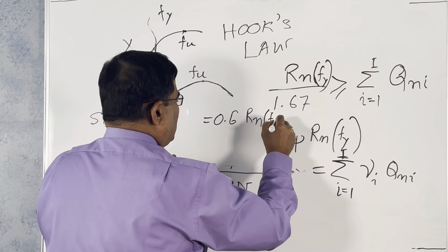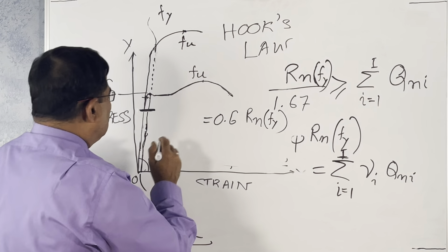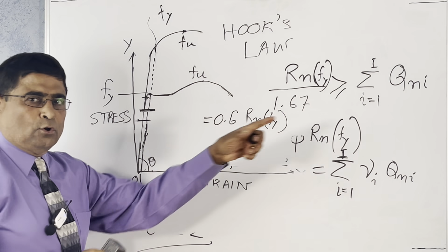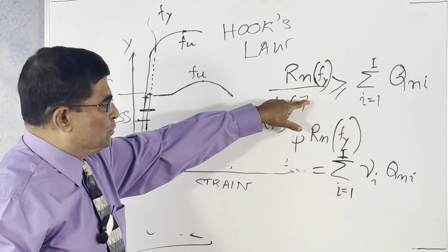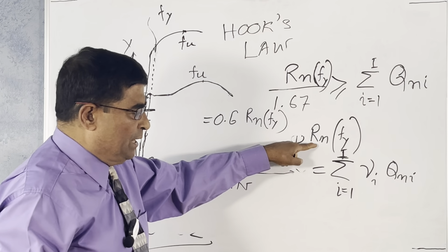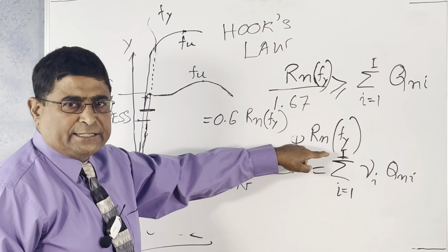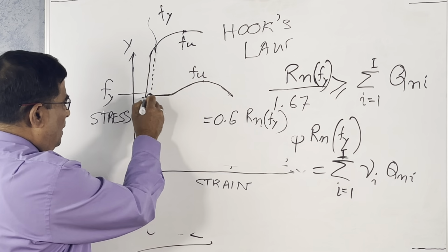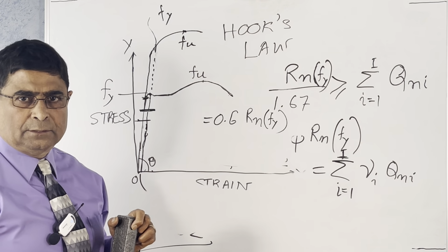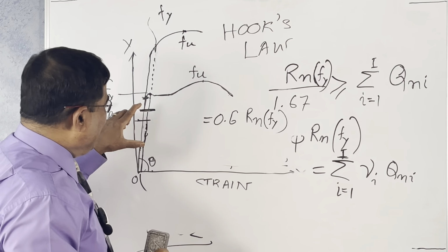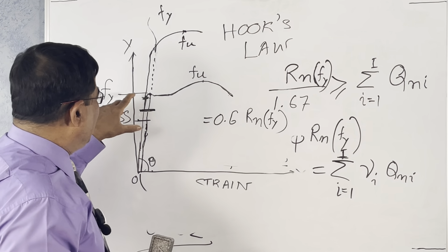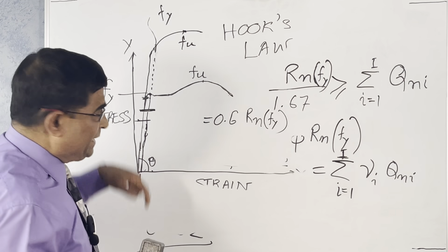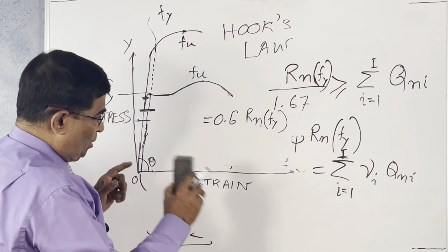This is a function actually. So that means we are somewhere here or here, depending on the load conditions. But we do not use working state design nowadays. We go for the limit state design or load and resistance factor design. So it is somewhere below the proportional limit. That means we do not like the structure to exceed the yield stress. It's below that. We do not go all the way to the yield stress. This is the first condition.